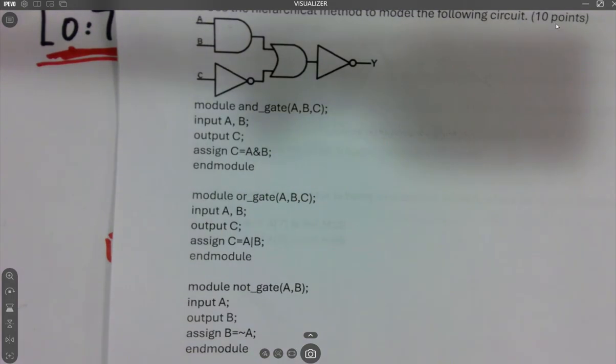So I'll let you guys start writing the top and bring all these together, and I'll let you tell me what problem you'll see. I do not need a second AND gate to be modeled. I can directly just instantiate it twice in my top, and you can make certain connections, sub-connections, in your top. I'll let you do it first before I show you the solution over here. How would you do it?